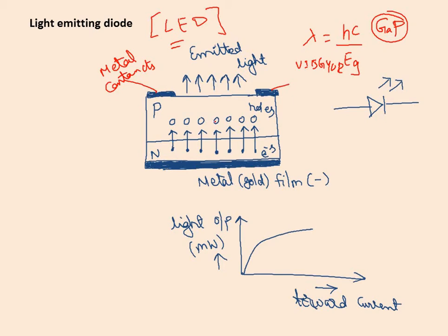When the radiation comes out, this film will reflect it. Preferably we use gold here. You can notice this is a specially prepared PN junction, because it is not like the normal kind. In a normal PN junction diode we don't have all these metal contacts. Such a specially made PN junction diode is nothing but our LED. Are we clear with this?